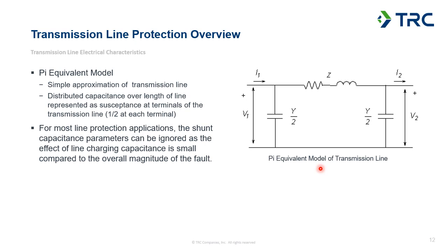I've got an electrical figure here of how we would model a transmission line, and you can see it's taking those parameters that we'd get out of that modeling software, that we've got a resistance and an inductance associated with the conductors, and that's again based on the mutual impacts between the conductors themselves, as well as the resistance parameters for the conductor based on the spec sheet.